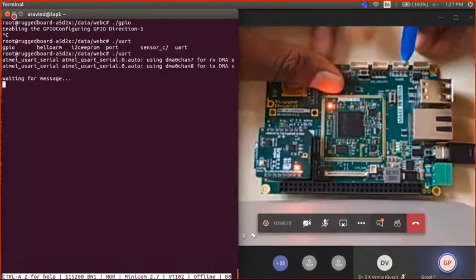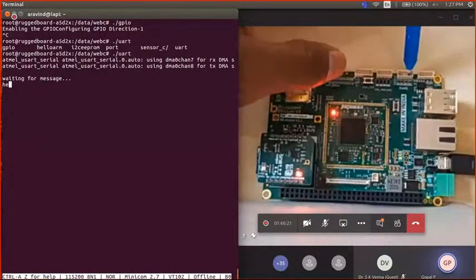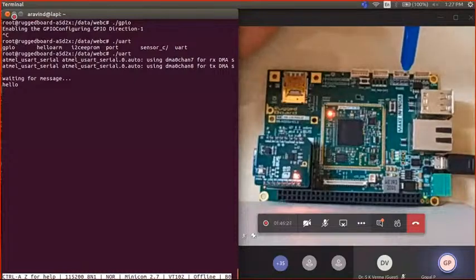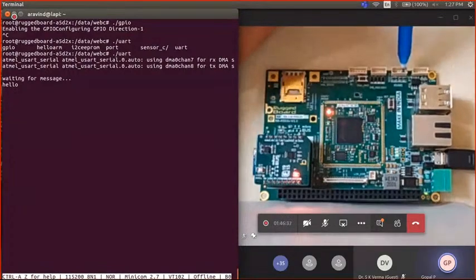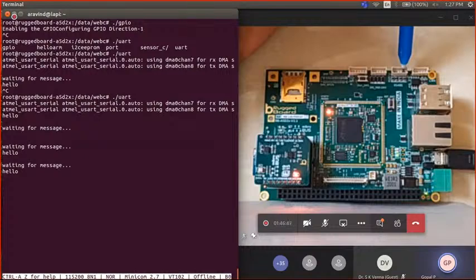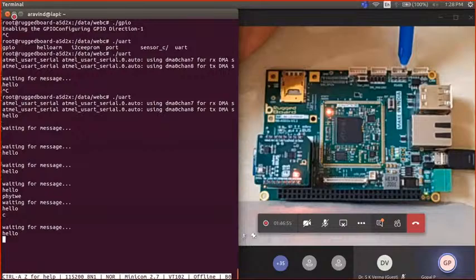In this, we are trying to show you writing messages. As and when you write the data on the port, it will start reading it. So it's a very superb application. You can enjoy a lot once you start two terminals. There is even a straight away demo we have on the board, with two terminals, UART S1 and UART S4. You can see in real time how we can make it up. One we can connect to the GSM, one we can connect to the GPS.